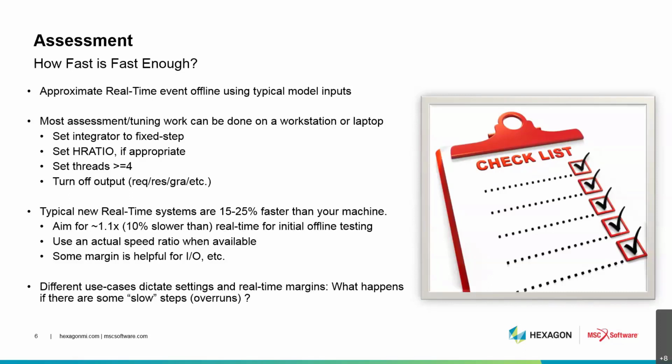You don't really want to set that up so that your model is running at 98% real time, because there are always a couple of little blips now and then that slow you down a bit, and you don't want to run over in that case. However, you also can keep in mind what happens when you go over. In some HIL scenarios, they track the overruns carefully, and if you have too many, the hardware shuts down, the cell shuts down, everything stops. That's a problem. But other software-in-the-loop environments or other situations are not so rigorous, and a couple of little glitches here and there are acceptable.